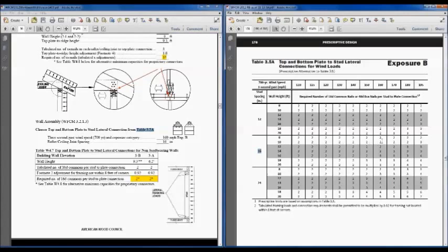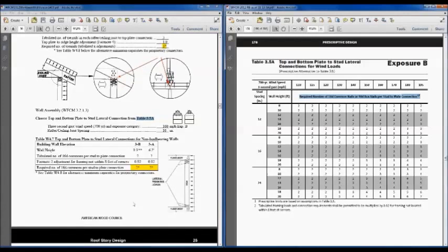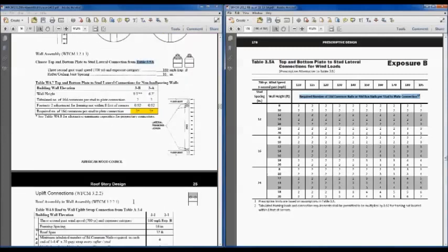requires 2 nails, and those are required number of 16 penny commons or 40 penny box at the stud to plate connection. So those are nailed through the plates into the studs, and so that helps with that load path.